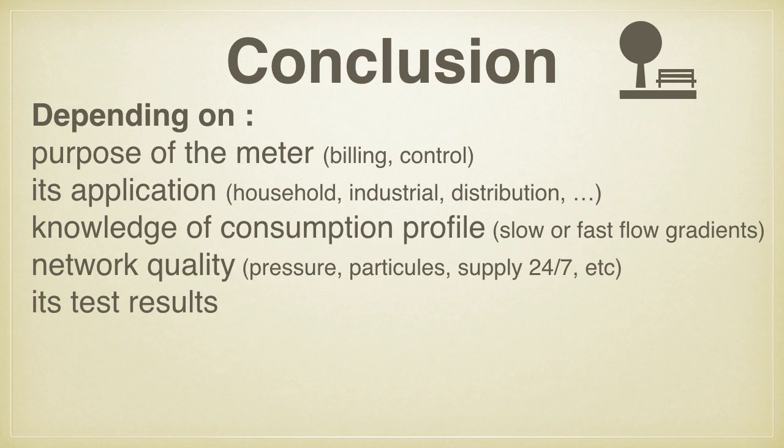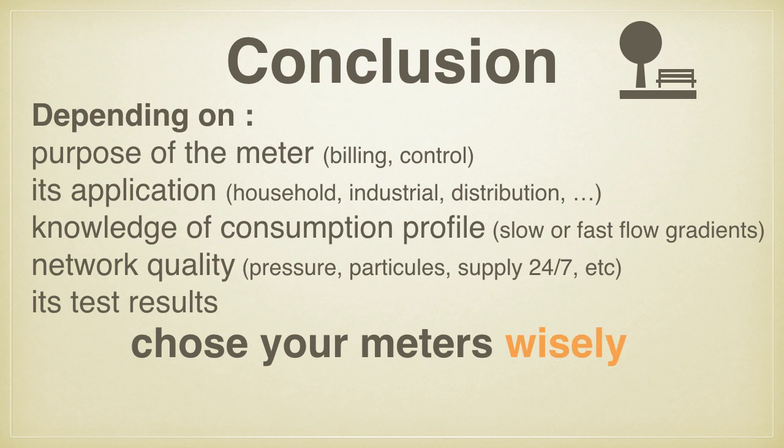As a conclusion of this session 4, depending on the purpose of the meter, if it's billing, control, etc., its application and the knowledge you have of the consumption profile of where it's going to be used, the network quality or the quality of the service, and specifically about its test results, you have to choose your meters wisely. And specifically, we point and advise to the static meters and the way that you select the static meters. Be very careful on the way that you select the meter and look at the sampling frequency it operates on. Not the sampling frequency during test, but sampling frequency during the operation while it's on the field.